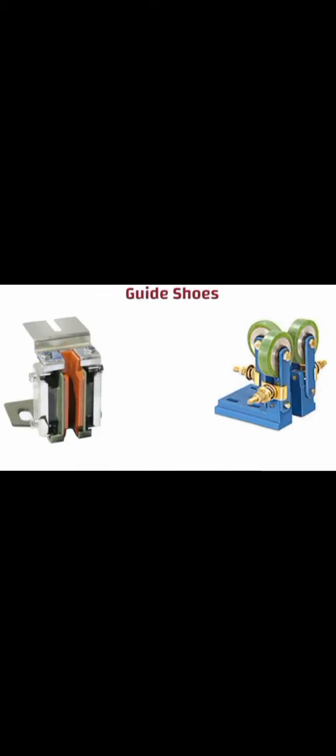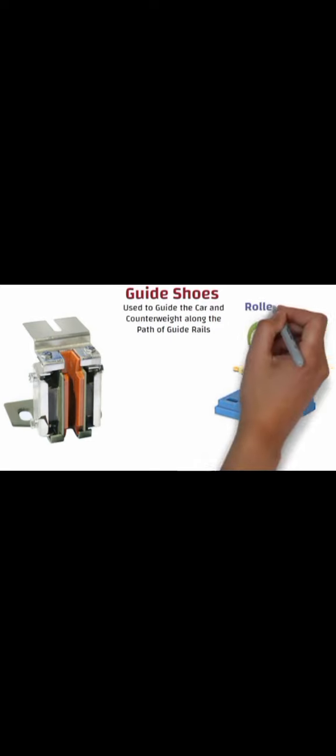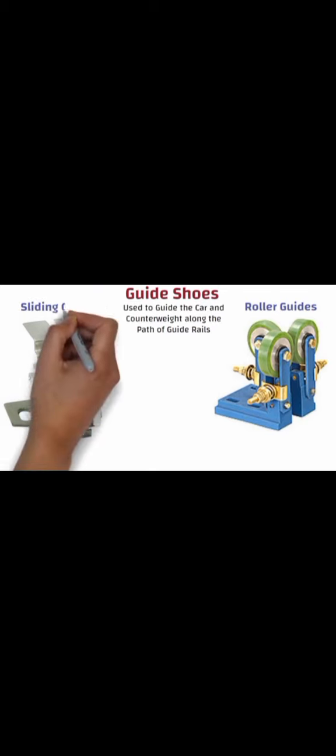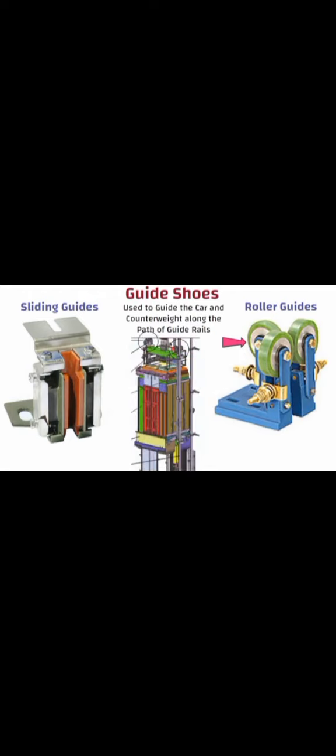Guide shoes. Guide shoes are the devices which are used to guide the car and counterweight along the path of the guide rails. There are two types of guide shoes. One, roller guide shoes, or roller guides, and two, sliding guides. Roller guides use rollers that rotate on guide rails. It has a set of 3 wheels that roll against the guide rails. You can see roller guide shoes on rails in this picture.